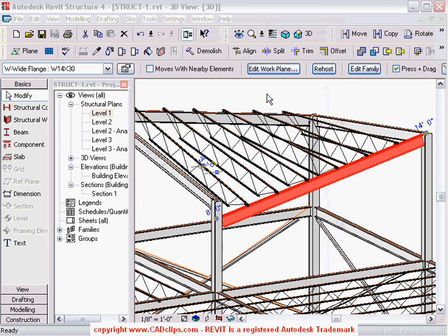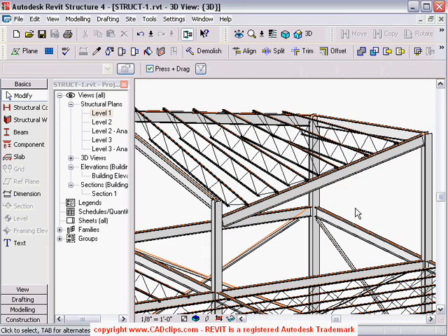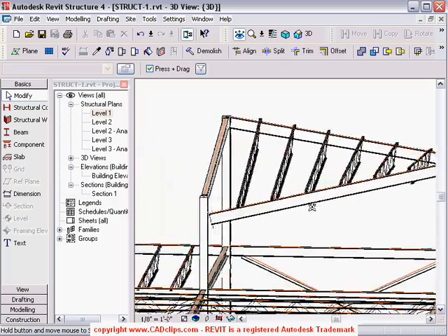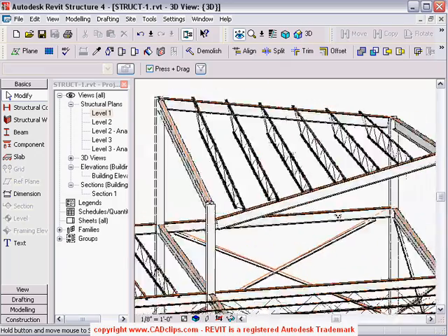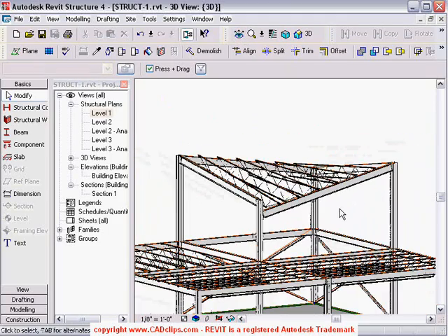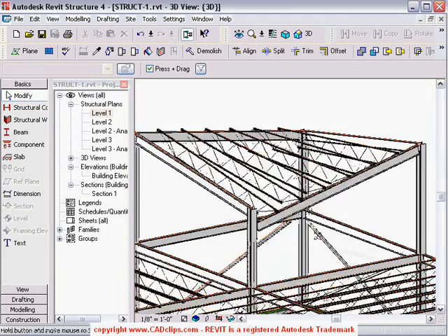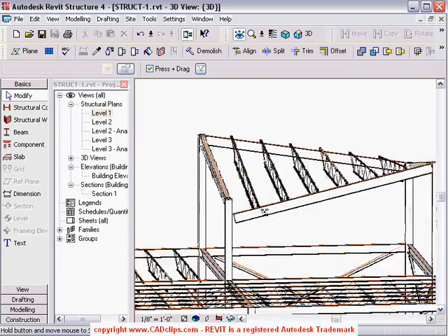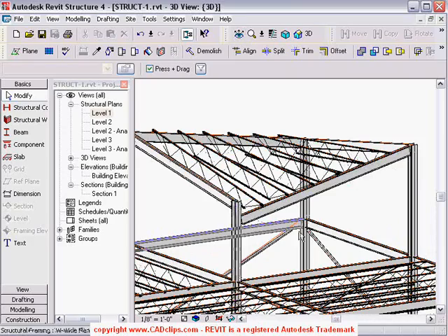And we can see there my beam got dropped down, not necessarily an ideal scenario, but fair enough. My joists, because that beam system is tied to this spandrel beam over here on the outside, are all going to slope with it. So there's just an example, an extreme example, I should say, of how that works. And then I'd have to tidy up this corner in here, okay?